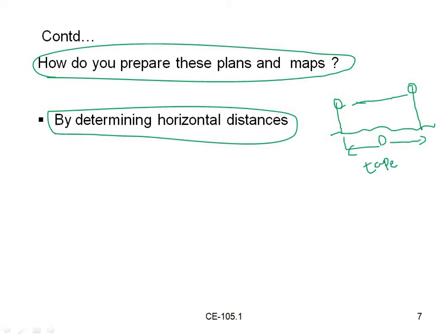You know the tape, which shows the measurements, or we can use an instrument to take the measurement of length. Or we use the surveying chain. A long chain made of mild steel, with lengths of 30 meters and 15 meters. We measure the distances from one point to another with the help of the chain. Those are called horizontal distances.